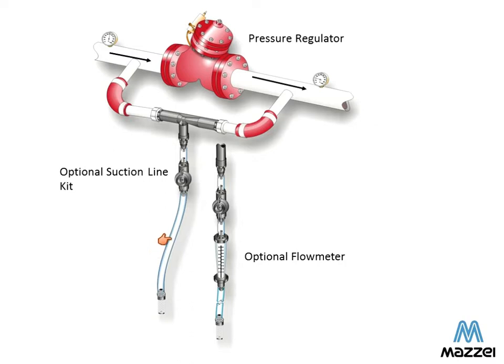Notice though that if you have a long run of suction tubing, you will have resistance to flow in that line, and that could impede your maximum suction capacity. So just be cautious of that. Also, if you have something that's very viscous, then you may want to step up your suction line tubing so that the viscosity of the material does not hinder the suction capacity as much.